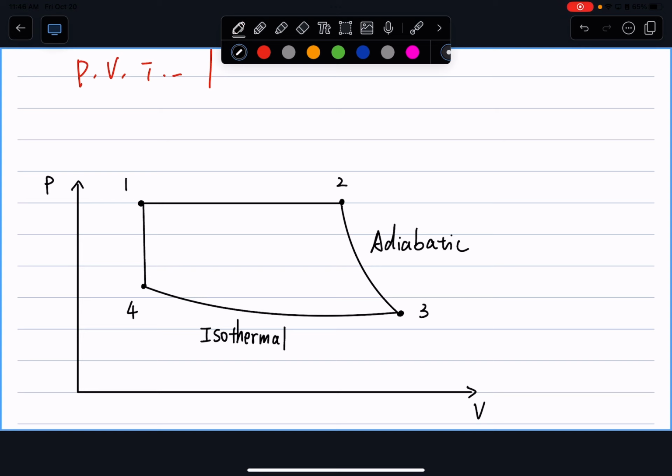By just looking at the PV diagram, can you tell me what kind of thermodynamic process we have? Right, so that's an isobaric process. And from 4 to 1, well, that's isochoric, where volume is the same. Now, adiabatic and isothermal, we went over that in the Carnot cycle. For the isobaric, what do we know about it? Now, what we have is P1 equals P2.